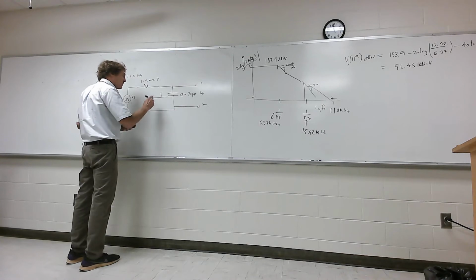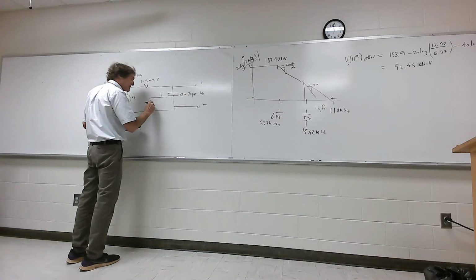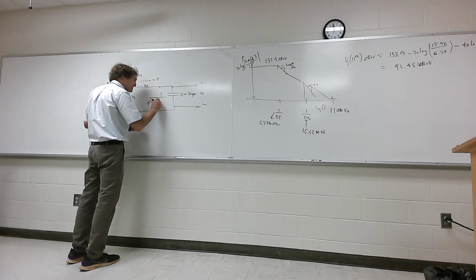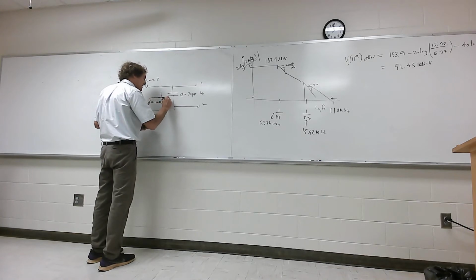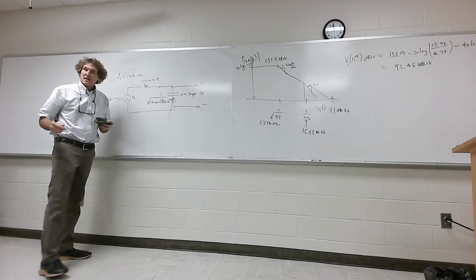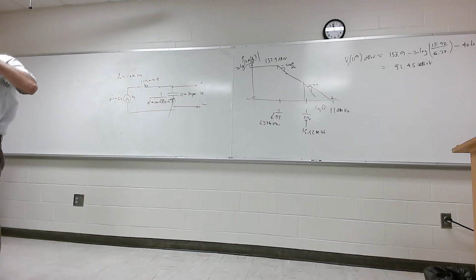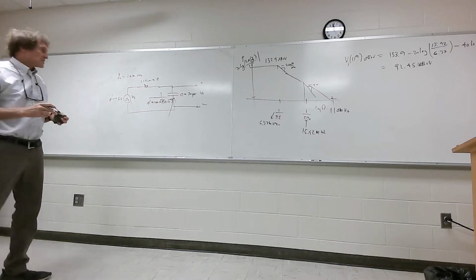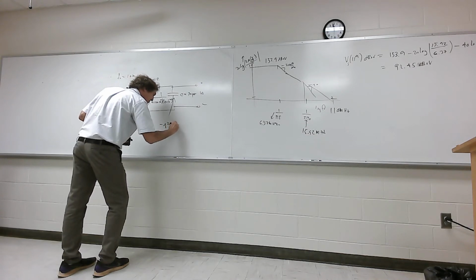That means it's going to be 1 over J 2 pi times 110 times 10 to the 6 times C, which is 70 times 10 to the minus 12. You can tell me what that is. Just tell me the value of that. Minus 20.7. Check it out. It's minus J 20.7, right? Minus J 20.7 ohms, right? Is that right? Okay. So this is minus J 20.7 ohms.